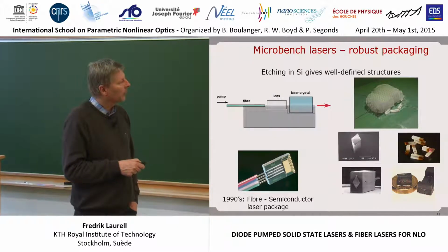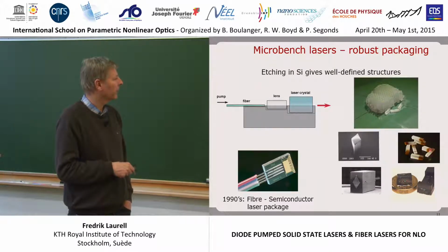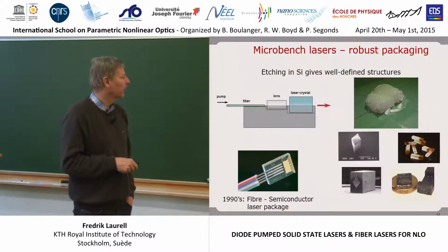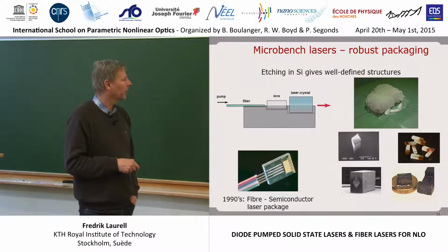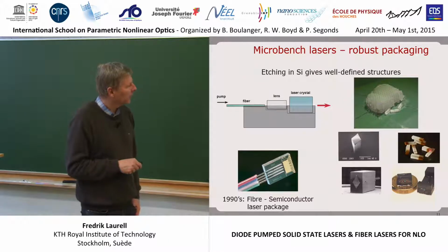Then, before you do that, you coat these crystals. And then you can integrate it on, for example, a silicon chip. And this is technology that was first used for fiber bundles for the telecom industry. So here are the diodes, and then the V grooves are etched into the silicon, and the fibers are positioned with micrometer resolution or precision.